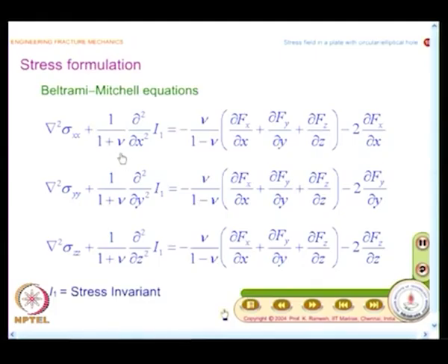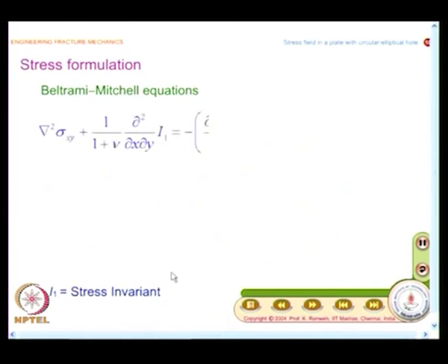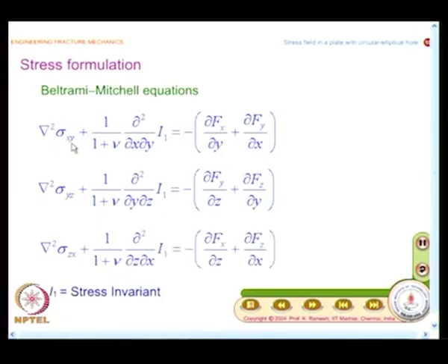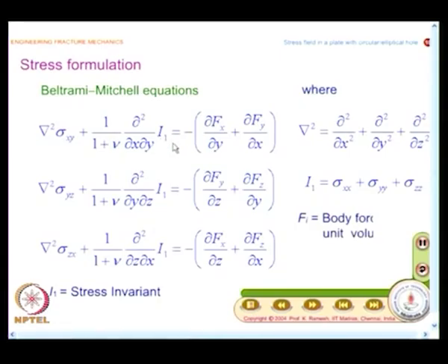So, the elastic constant of the material comes into play when you are looking at a 3-dimensional problem in the absence of body forces. So, I have 3 such expressions, I will have 3 more such expressions involving the shear stress quantities. They are del squared sigma xy plus 1 by 1 plus nu dou squared by dou x dou y into I1 equal to minus of dou fx by dou y plus dou fy by dou x, and these are cyclically repeated,